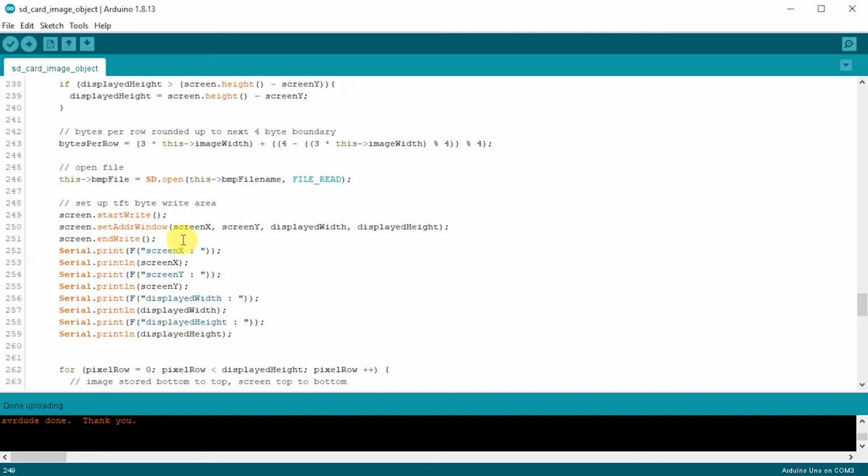And it's important you do that, because obviously if we leave the channel open to the LCD screen and then go off and try and access the SD card, our hardware is going to get confused as to which SPI device we're actually talking to. The higher level functions in the graphics library handle all this for you, but now we're working at a much lower level. We need to start initiating these conversations and closing these conversations ourselves.